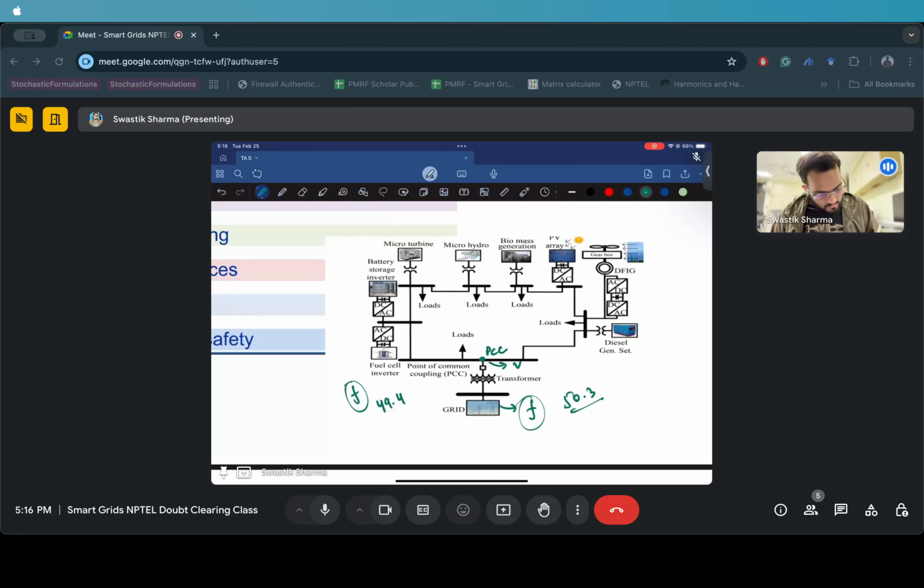Now the inverters, let's say this inverter, uses feedback from this PCC. It uses feedback to match the frequency and voltage levels of this point of common coupling, right? Now this inverter could also go out of sync, and this could cause unintentional power quality issues like reactive power problems, voltage falling down to the lower limit, or some other power quality issues.